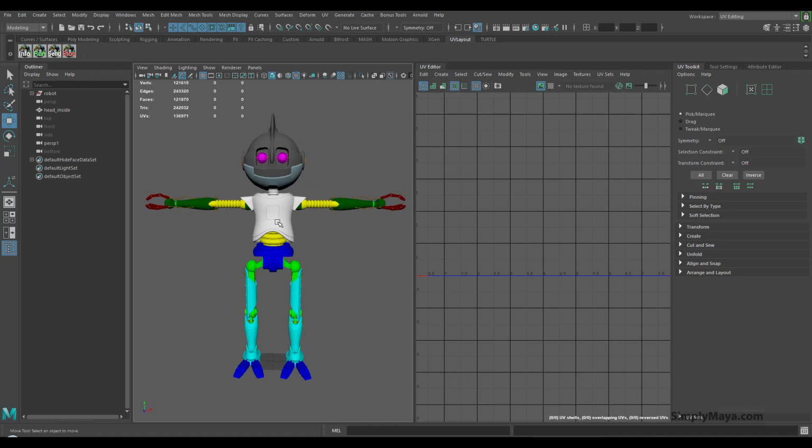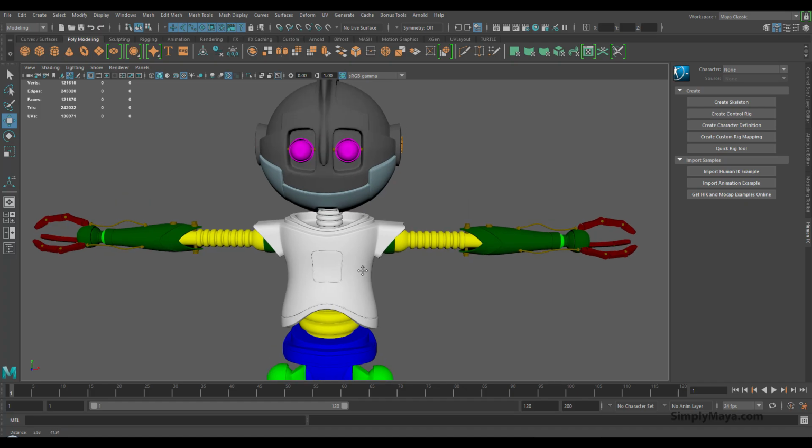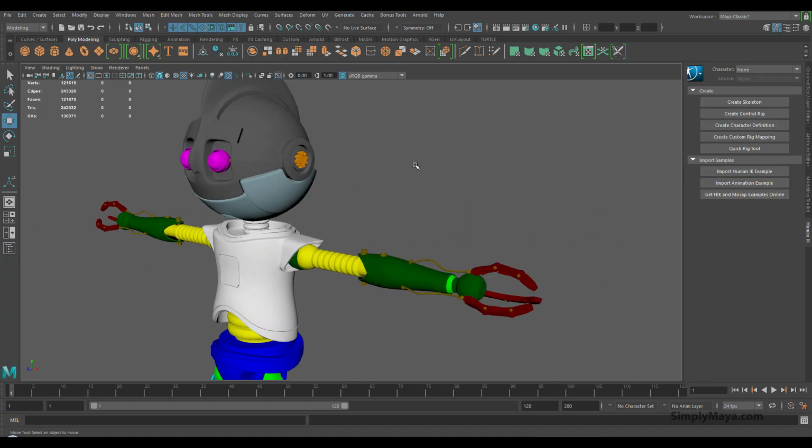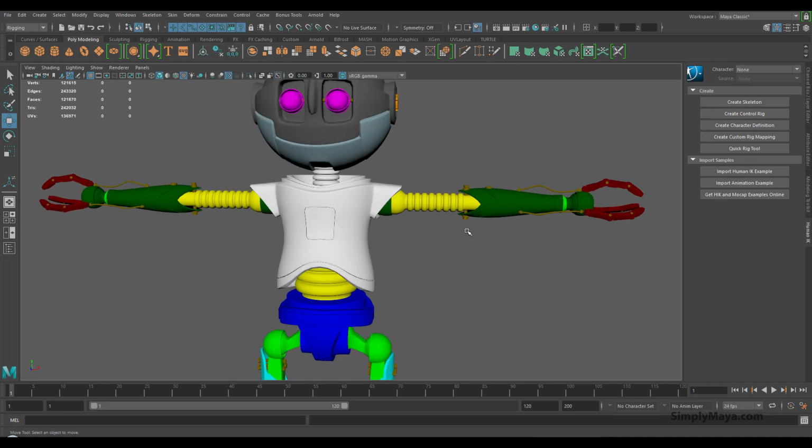Now for posing, a quick rig will be fine, and as we've got a humanoid shaped character, I'm going to use HumanIK. So I'm going to make sure that I'm displaying HumanIK. I'm going to set my workspace back to just classic, and I've got HumanIK open here on the side tab. If you don't have this, you can set your menu up here from modeling to rigging and go to skeleton, HumanIK, and that will drop the menu in for you.